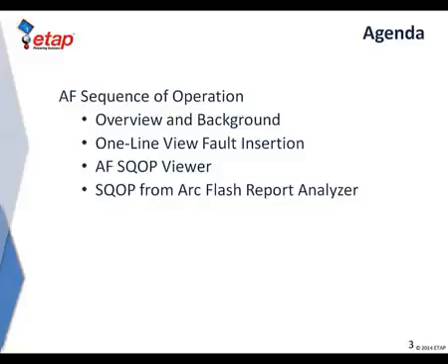So why and how can you use arc flash sequence of operation? Well, there are three main functions that this tool serves for the analysis of arc flash. Function 1 is that it can be used to simulate overcurrent protective device operation under changing fault currents, also known as fault current decay. For example, systems with a lot of motor load or faults near the generator will experience a significant decay in current.